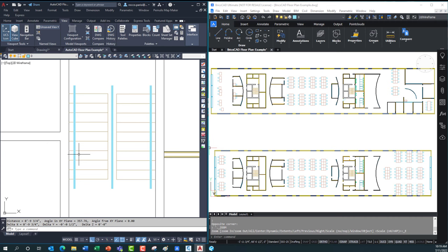And the architect now says, hey, you know what we're going to do? Let's change up our design, and we're going to go down to just kind of a glass partition that goes up through the walls, right? Get a little bit more light in here, make it a little airier. So the gap here only needs to be, we'll pull 6 inches off, right? We're going to stretch each side of these 3 inches over. So I'll just pull this over 3, and I'm going to pull this over 3. We have a much smaller gap. Simple enough to do, right?